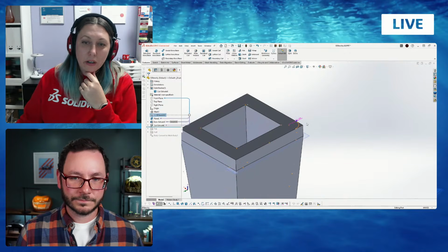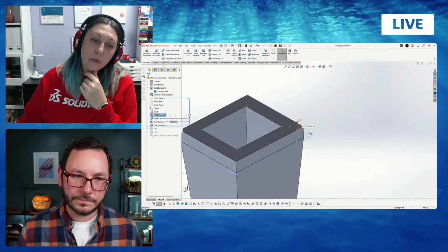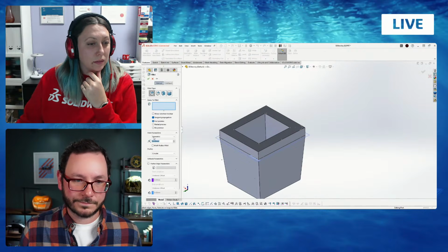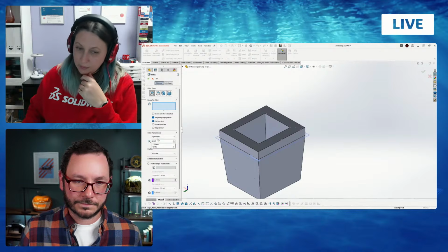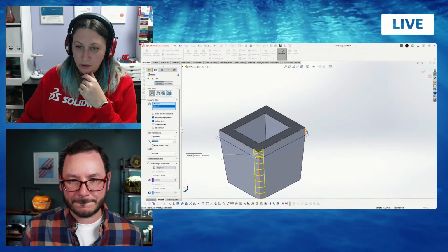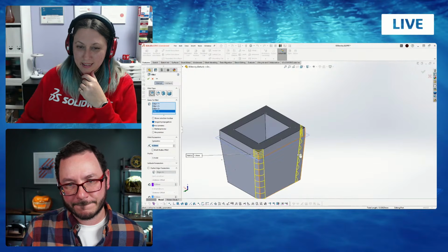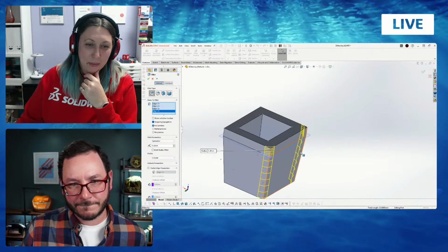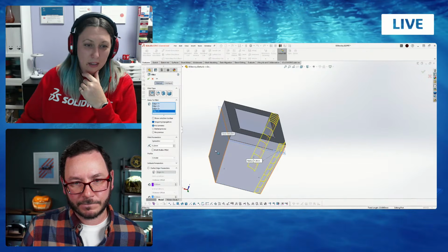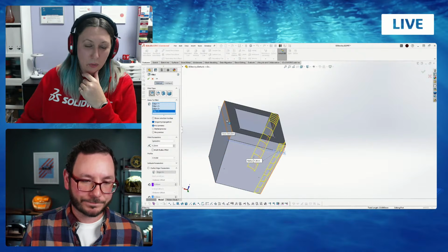We had the 3D sketch. 1.28 is the radius we have. But I made a small mistake. I don't know if you noticed. When I made the boss extrude, actually I used an angle, but this should be straight with that one.